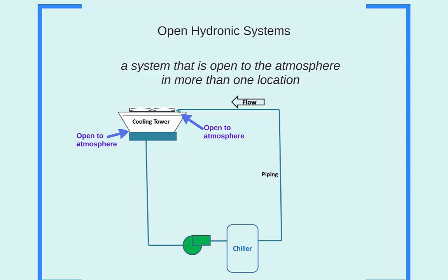The issue with open systems, and condenser water loop systems in particular, is that there is dirt and other crap constantly getting into the hydronic system. Thus, appropriate treatment is required so that the stuff doesn't clog up our system and make it operate inefficiently. Additionally, in the case of the condenser water loop, water is constantly being evaporated out of the system as the stream trickles down through the cooling tower, and thus we need to replace such evaporated water. This constant introduction of makeup water from the domestic water source means that we're constantly bringing in more entrapped air. Oftentimes, an air separator isn't even placed in the system since it would just be fighting a losing battle.